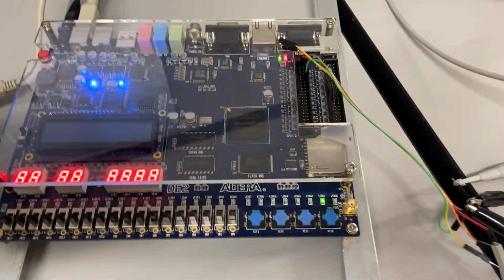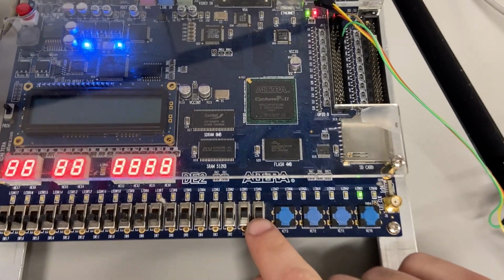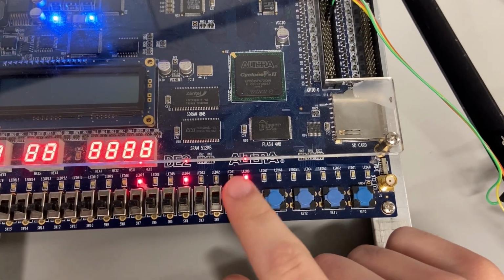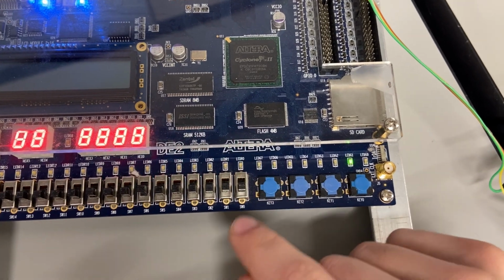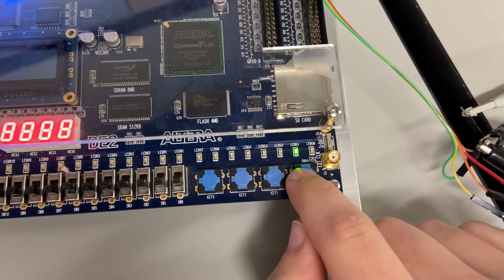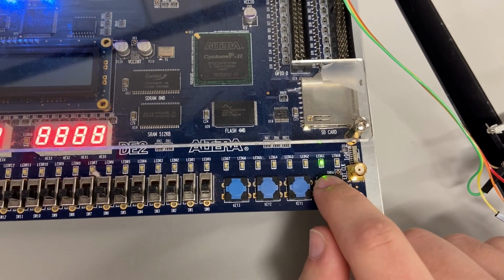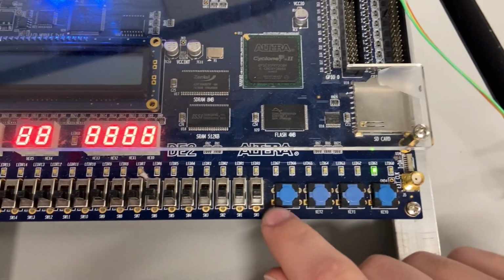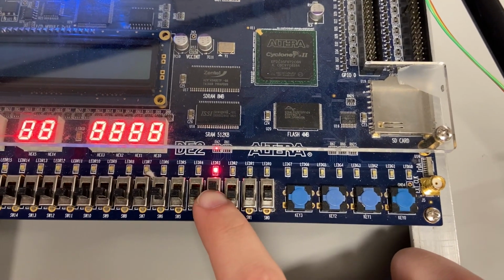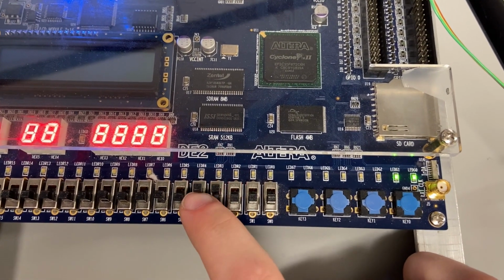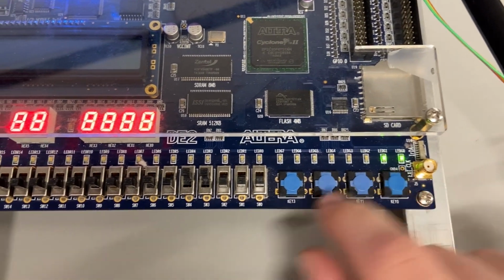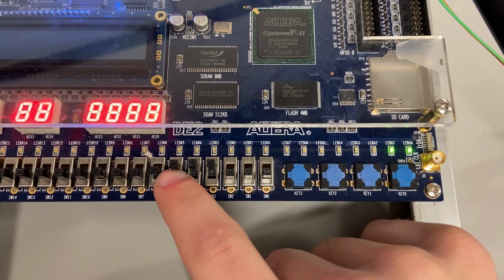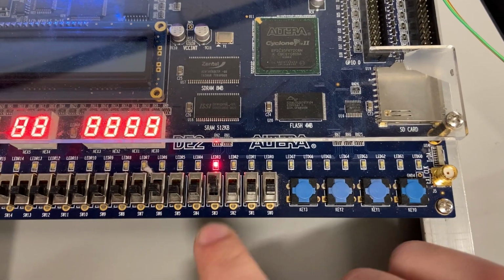Moving to the hardware test, we can see that now the Altera board is being silly and it's throwing a bunch of random LEDs that aren't set for anything, so ignore that. But this LED is showing that this is our 0 flag. It's showing that there's nothing going on here. Now if we have our main bit high and we shift it to the left 1, we can see the 0 flag and the overflow flag both kick. If we shift it 2, it does nothing because we're not rotating.